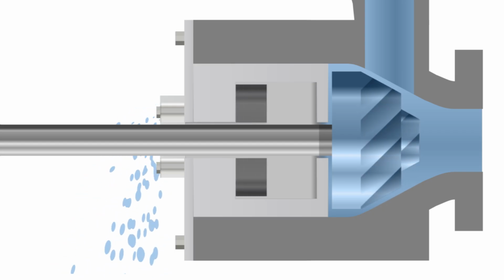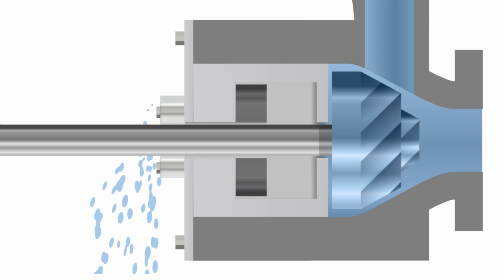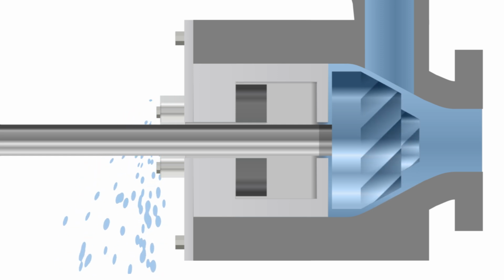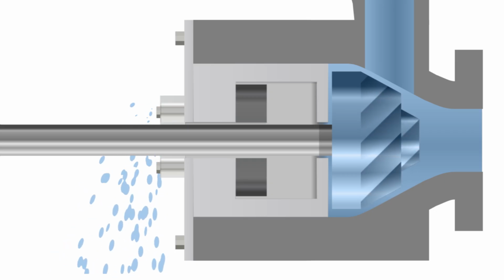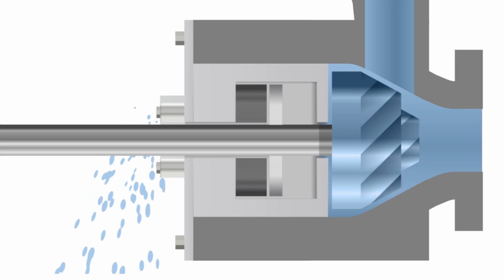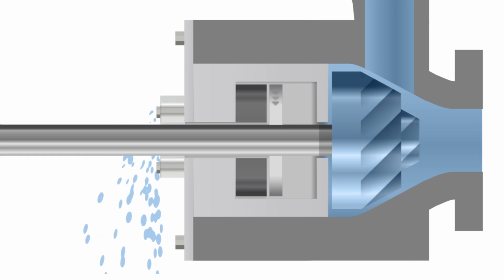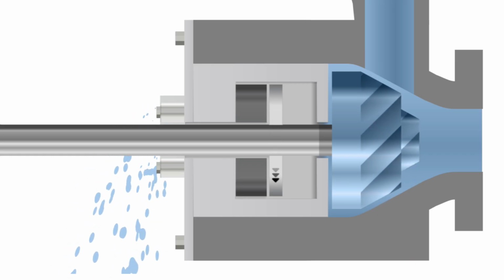The first is called the mating ring or seat. The mating ring is fixed to the inside casing of the pump housing. In this example, the mating ring is static. The second component is called the primary ring, or face. In this example, the primary ring is attached to the rotating shaft.